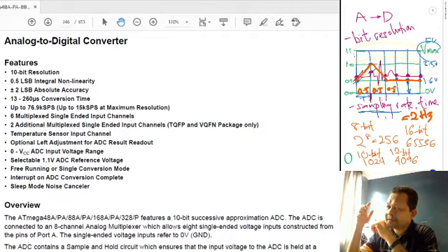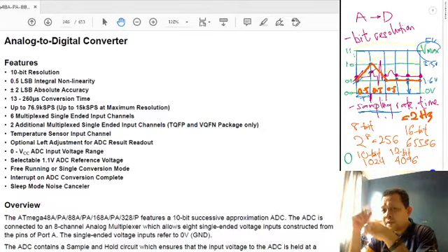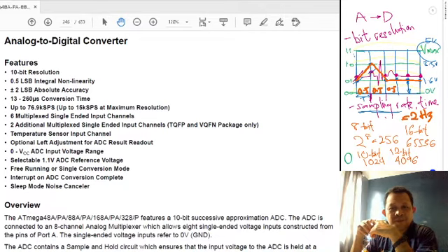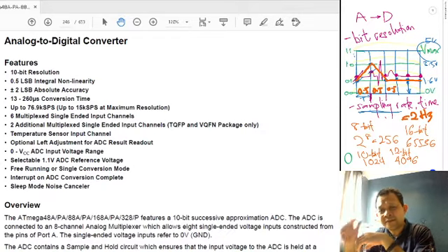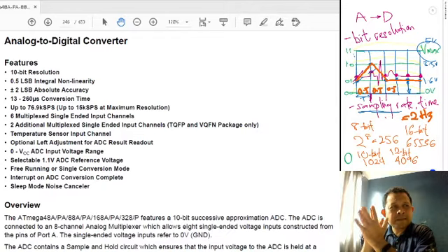So even though you can have a 100 bit ADC, or 1000 bit, between those bits you still have voltage levels, but the voltage levels will be very small. Even if you convert even deeper, one trillion bit, 1 million bit, so 5 divided by 1 trillion, you still have some voltage levels. So when you convert to digital, it is already discrete. Voltages are discrete. You will never be totally the same as the analog. But the thing is, how much error, you call it the quantization error.